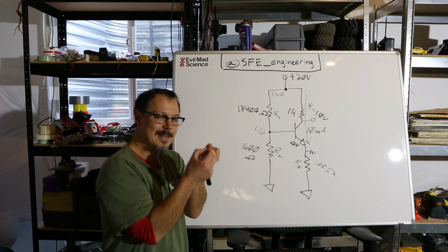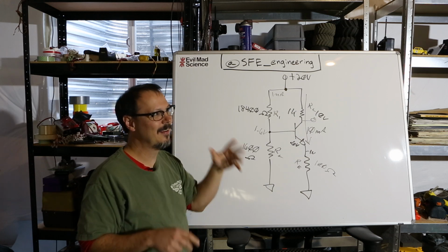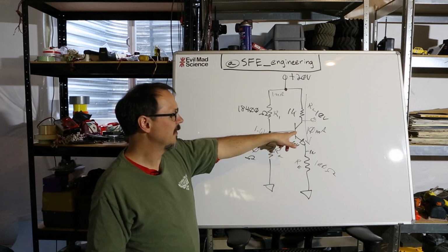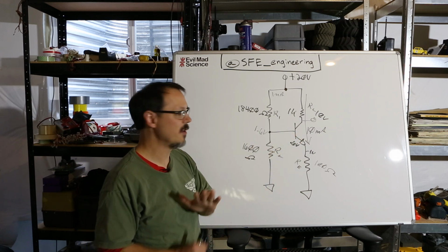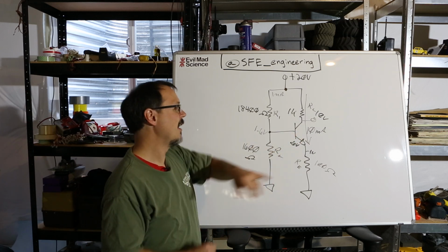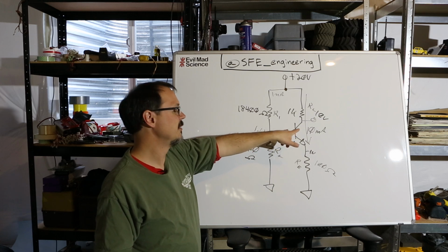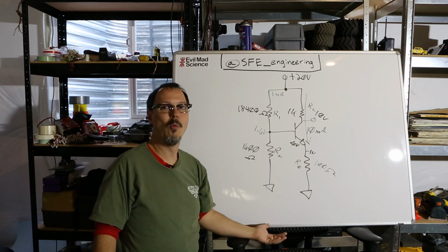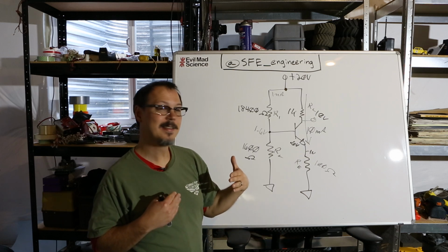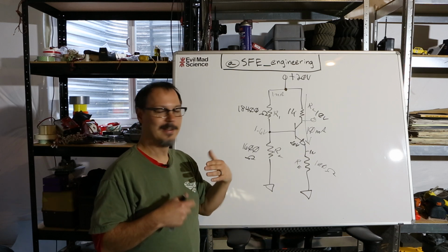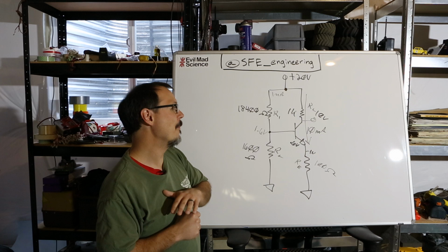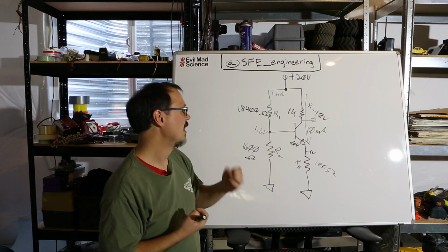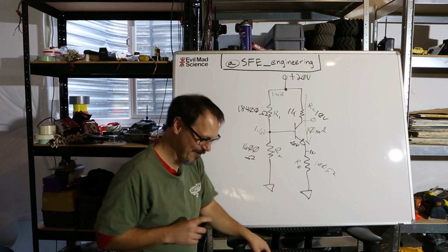What's that? This little part, TO-92 package, right? It's a teeny little guy. I'm about to compare it to 2 quarter-watt resistors. This little package is only good to about 625 milliwatts, okay? And I was trying to run this thing with 10 volts and 50 milliamps through it, so I'm running half a watt, which is below its max, but it sure didn't care for it, as evidenced by the brilliant smoky aroma that was soon to emit from this thing.